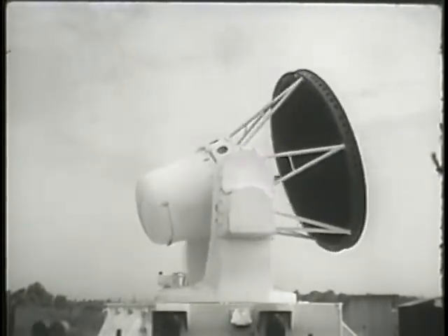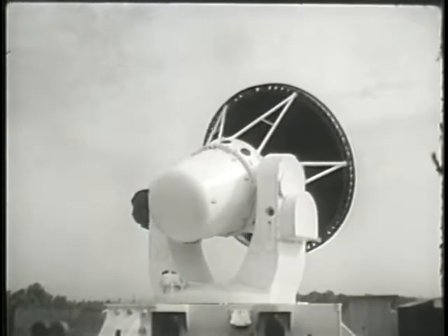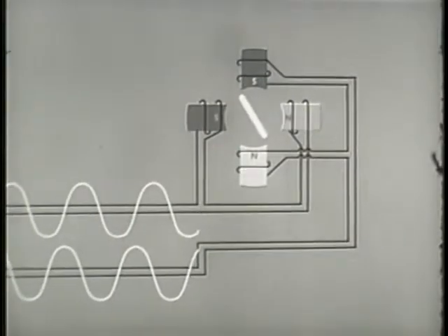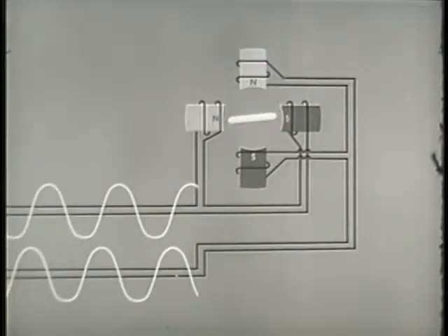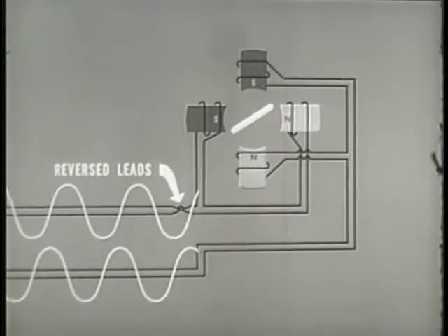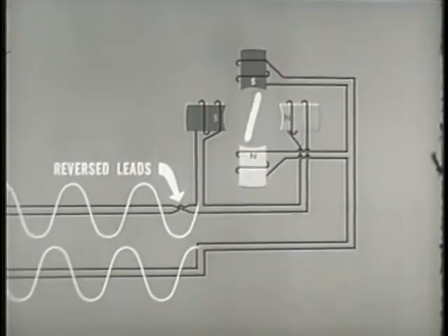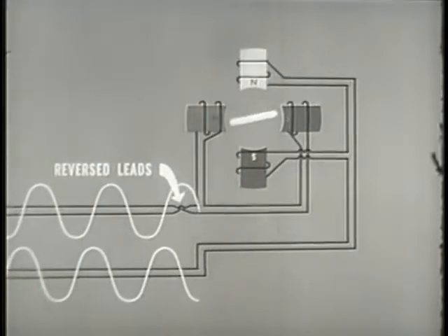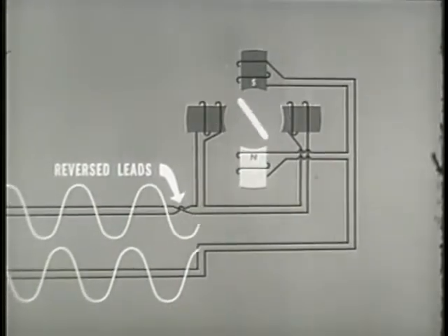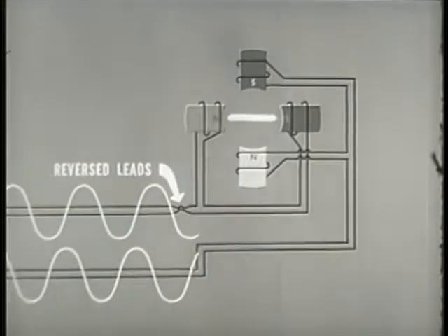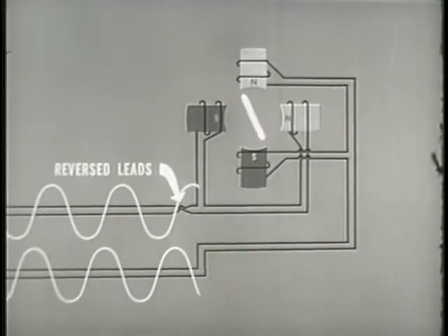The two-phase motor in this installation is called on to change its direction rapidly. This rapid change of direction is accomplished simply by reversing the polarity of only one set of poles in the motor. The polarity of the second set of poles will remain unreversed. The field will now rotate in the opposite direction, with the rotor following at a slightly slower speed.